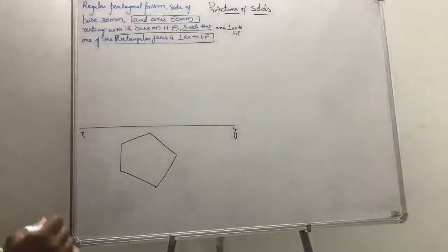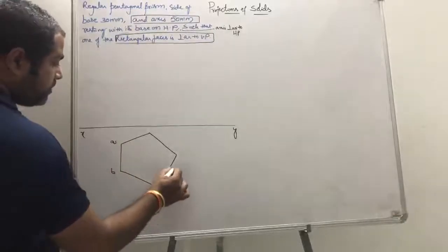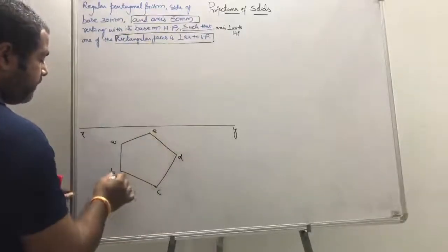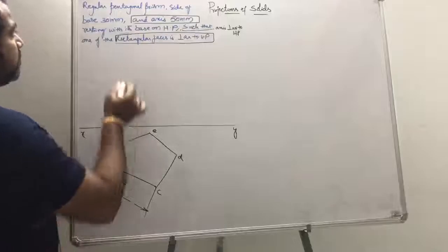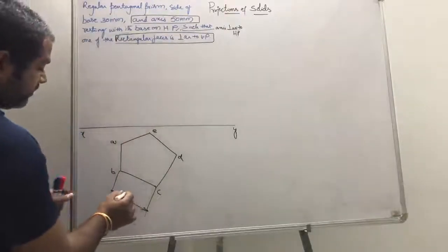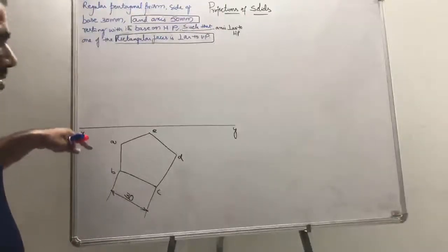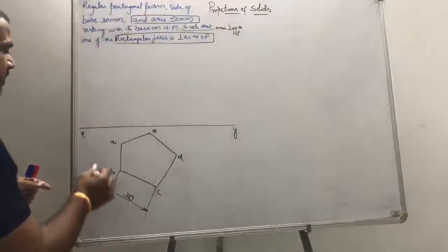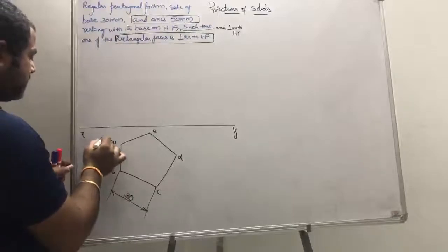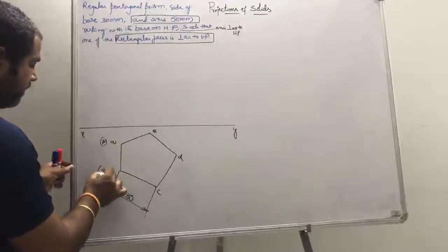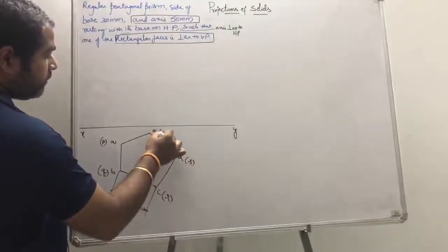Okay. Now mark the points A, B, C, and also in the top view you are going to obtain the true size and shape. True shape was base 30. Okay, and here it is a prism. So particularly I get the double points. Why? Because the top base is visible, the bottom base is invisible. So I just place it as bracket P, Q, R, S, T.